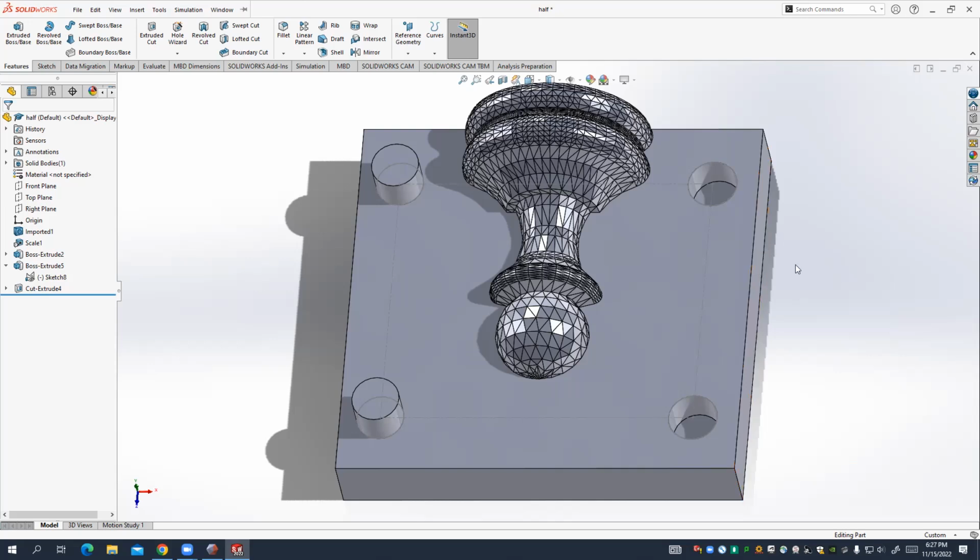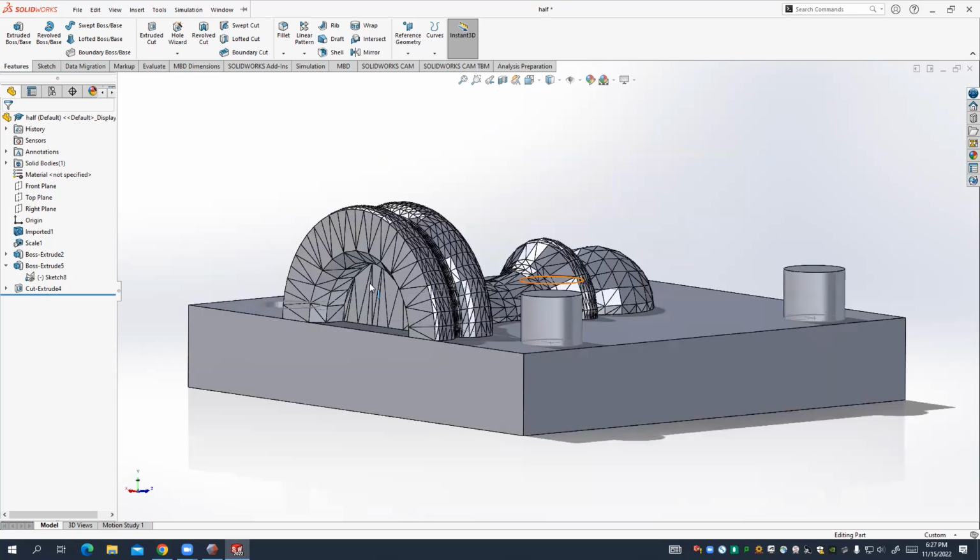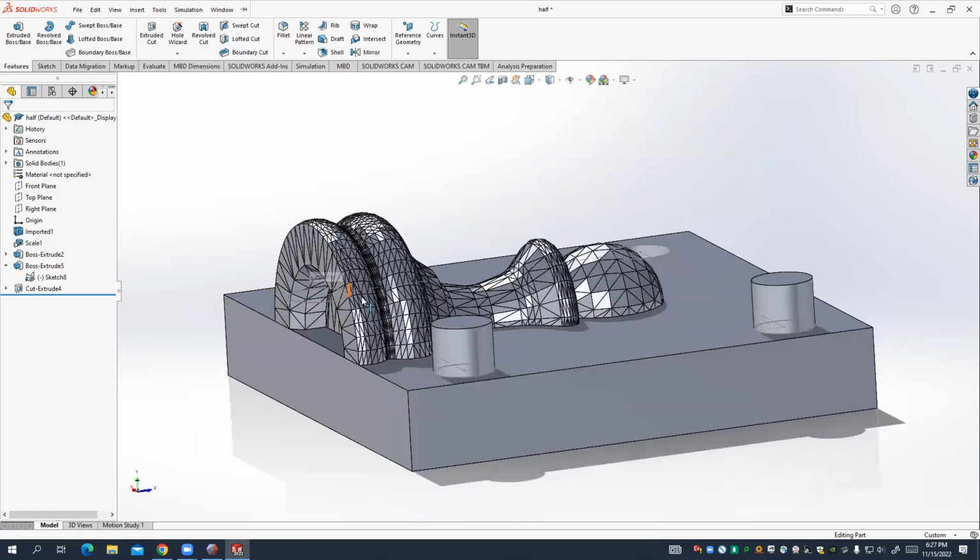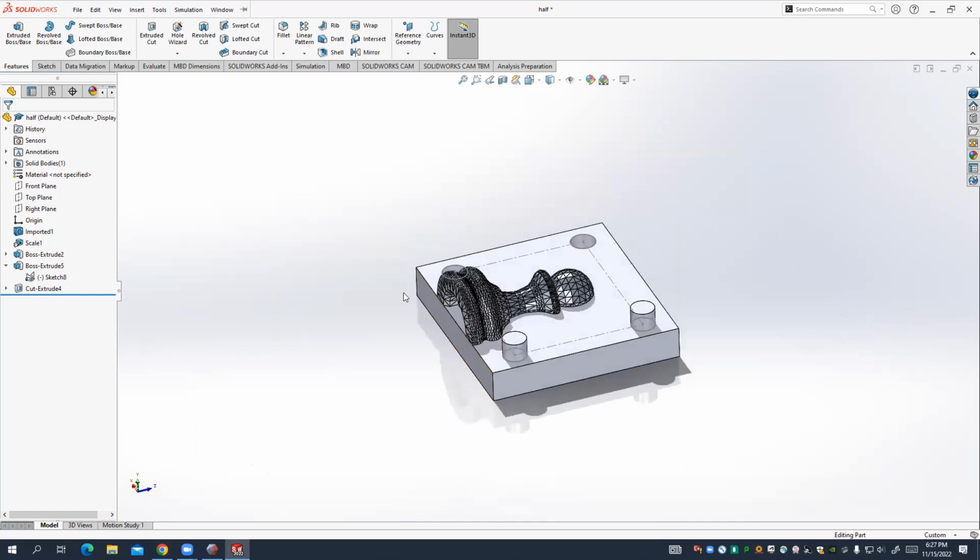So yeah, assuming that your part has a flat base, how this will work is if I have my two molds, I can put them together and I can pour directly in and leave this level off as my flat base. If your part does not have a flat base that you can use to mold, actually how about this, raise your hand if you don't have a flat base on your piece. Okay, Daryl, so what you can do is just add a pour hole.